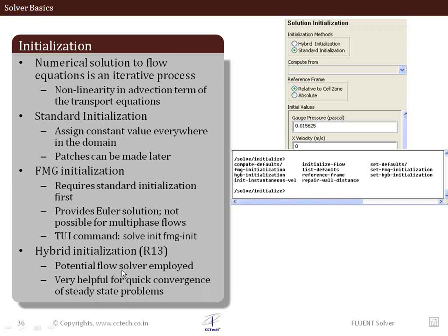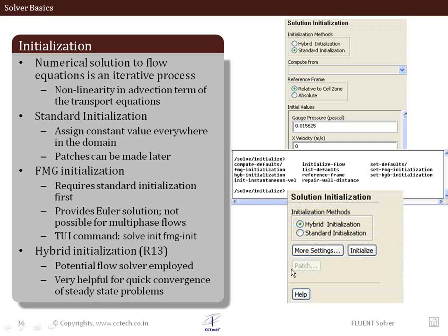So this is very helpful. It's a new feature in ANSYS release 13, and how it is done is that we just choose the hybrid initialization option and we say initialize. We can also modify some settings by going to the more settings option which is available.